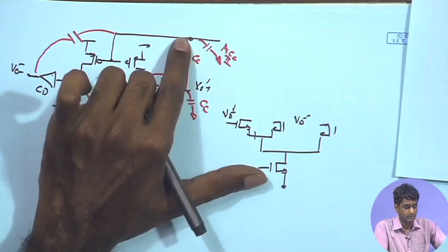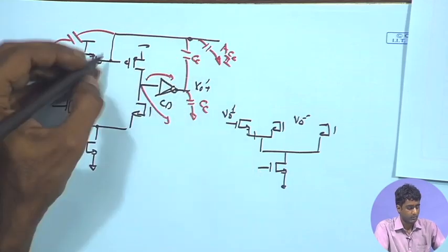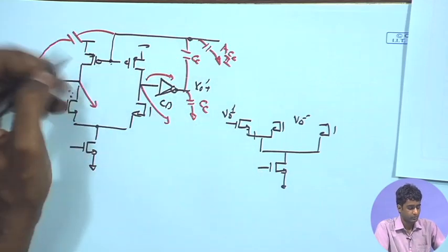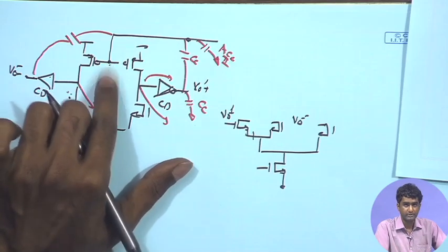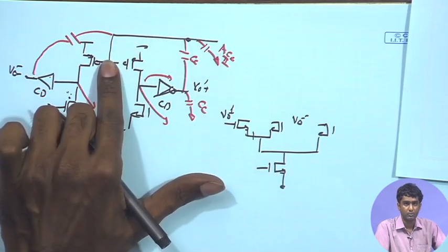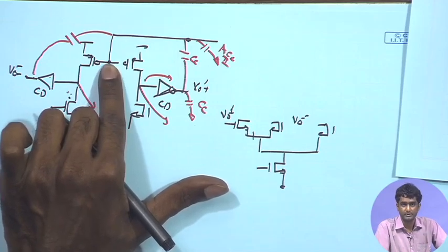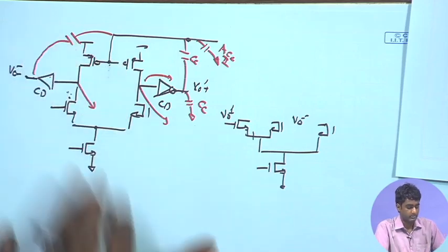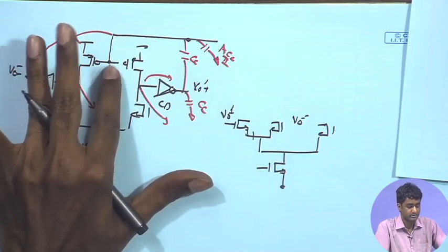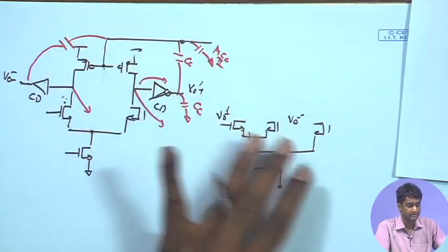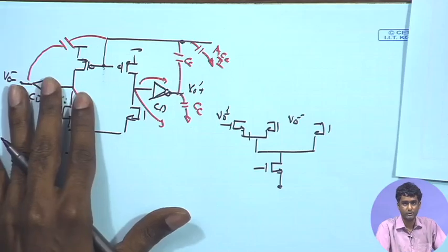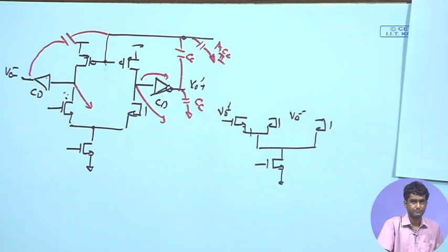It is just influencing the common mode node over here, and even if this node happens to have a larger capacitance, we do not really worry about the speed of this common mode, because this is just a DC bias point. So, it is not an important concern in this particular application, where we are just concerned with establishing a DC bias with the help of common mode feedback. So, this is another point to be noted.